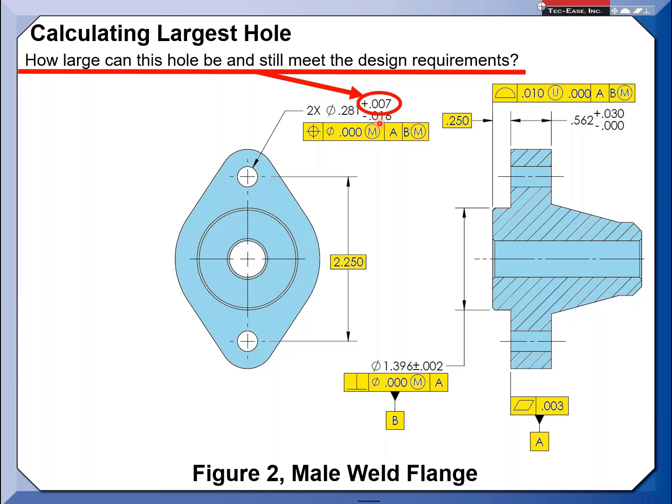What we're going to be looking at is the head contact area mating against this flange. There might be some design requirements: area contact, loading, torque. So there's a whole plethora of other possible requirements that might determine how large that hole could be. I didn't really address those. I just asked how big it could be without going underneath the head.